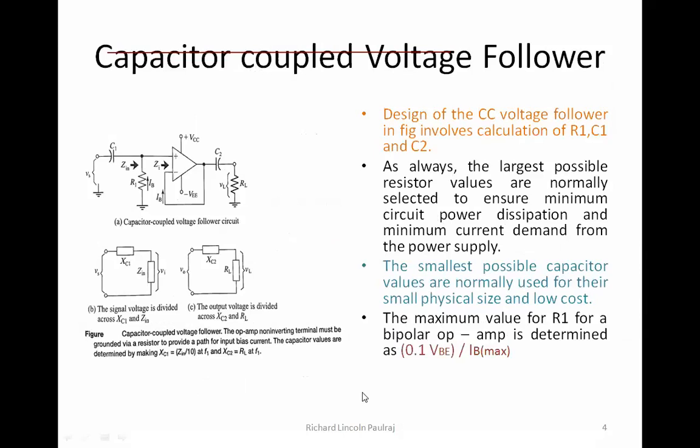This is what I was talking to you about. We are just looking at this circuit here, the capacitor coupled voltage follower. You can see that we do not have a capacitor here, nor an extra resistance here. Those are the things which are added when we talk about high input impedance. Fine, we will move forward.